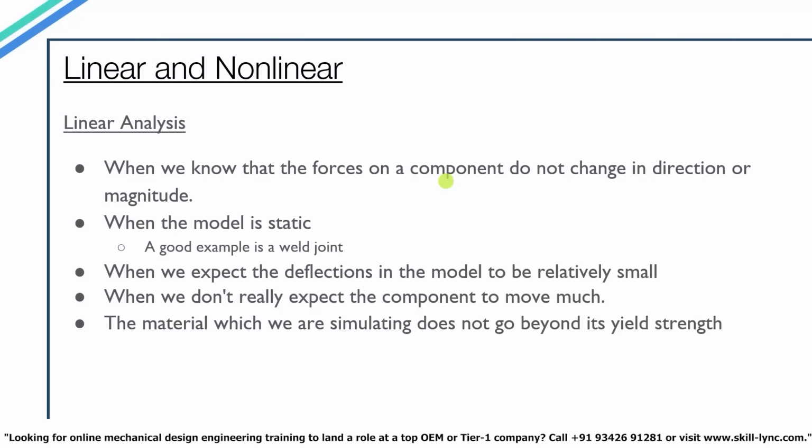Another place where linear analysis is used is when we don't really expect the component to move much. The last major assumption is that the component we are simulating does not go beyond its yield strength. So in this case, where exactly will we be using a nonlinear analysis?